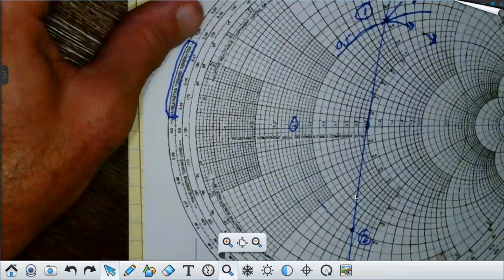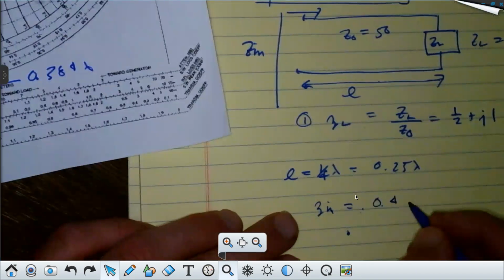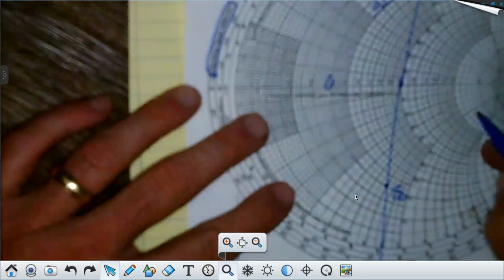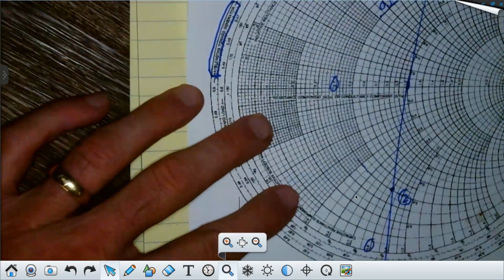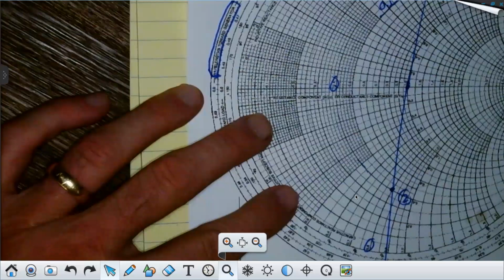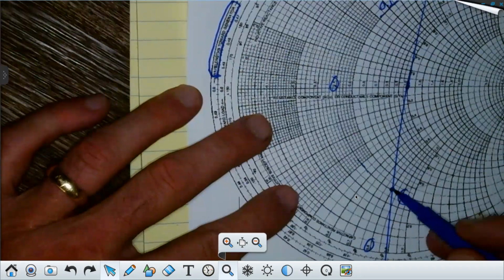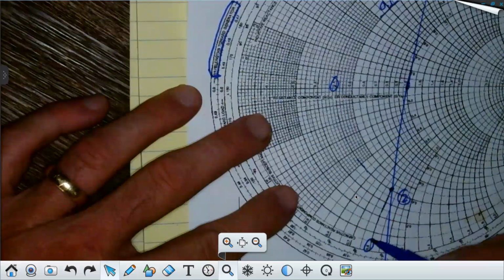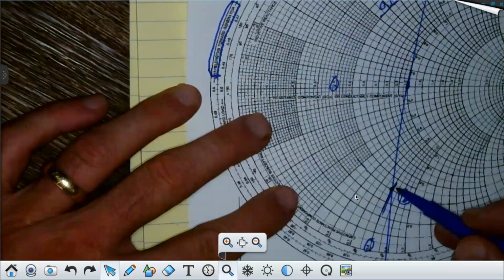So for here, when I look at now my Zn, that's normalized Zn, it's 0.4. And what's the imaginary part, class? Come down here and you get, that looks like 0.8, isn't it, class? You see that? Can you all see if you take this point and you trace out the line that intersects it right here, this is going to be a line that always comes in perpendicular to the outer circle, and these are the imaginary components. Here, do you all see 0.8?